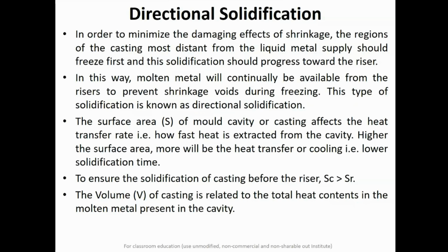So if it is happening like that, the riser is not solidifying, but the casting is solidifying continuously. In this way, the molten metal will continually be available from the riser to prevent the shrinkage voids during the freezing. And this type of solidification, in a particular direction, from the casting to the riser, is known as directional solidification.